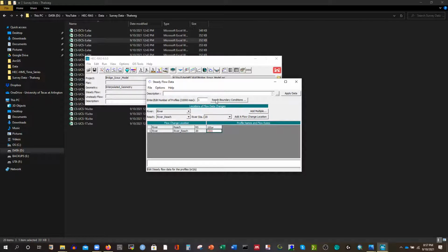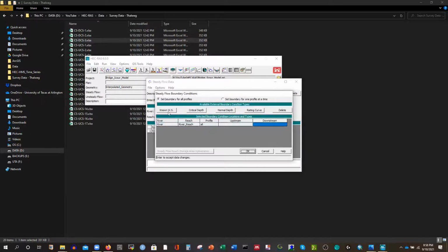You can add that. And if I want to select that reach boundary condition, okay, reach boundary condition, then what will happen? We need to provide the downstream boundary condition. See, by default it is showing the downstream boundary condition here. So when I am selecting that downstream boundary condition, you can give known water level, because we have the known water level for 100-year return period.